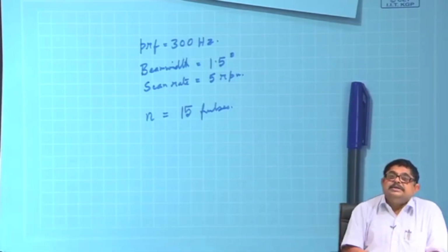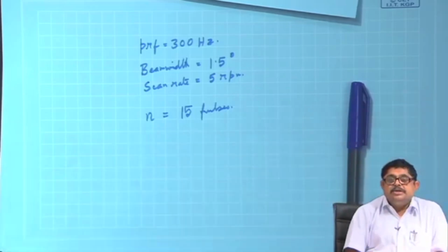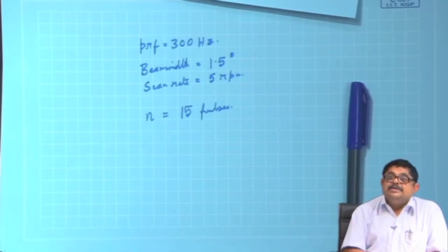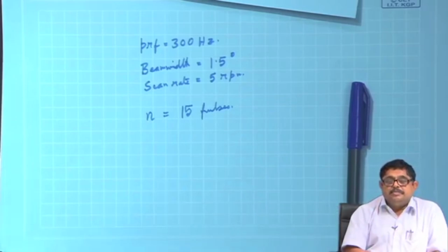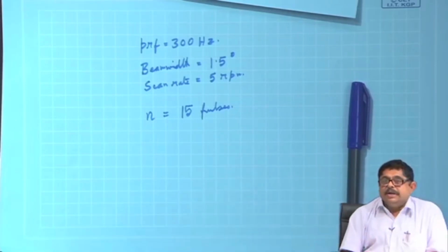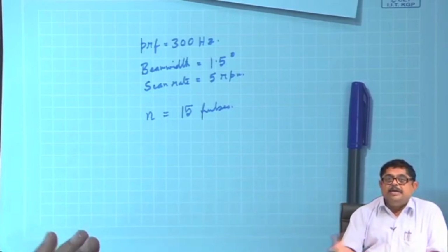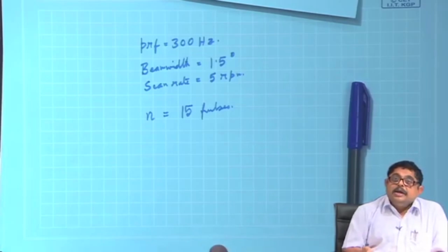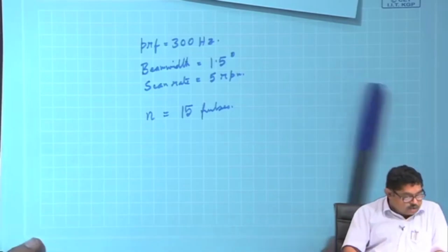But in a noisy system, people may say that it will deteriorate your detection because your noise will increase, but the answer is no. If you do it for zero mean Gaussian noise or very low mean noise, it will actually improve the SNR also.